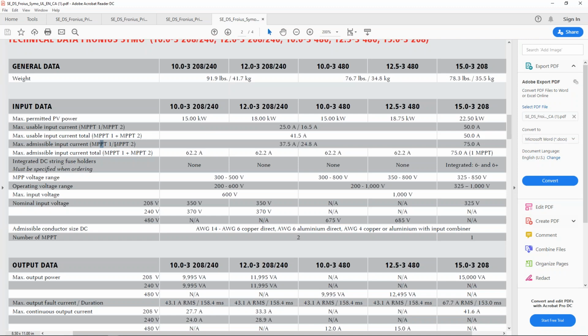We have an MPPT1 and an MPPT2 circuit. Just like modules have their own maximum power point for voltage and amperage, the inverter has its own maximum power point for voltage and amperage. If your inverter has 2 maximum power points, that means it can handle 2 different inputs independently of each other. They can have an east-facing array and a west-facing array. They could have a shaded array and an unshaded array and manage those 2 sections independently. So string inverters have, in their own right, gotten more shade tolerant. Back in the day, you did not have inverters with multiple power point tracking.